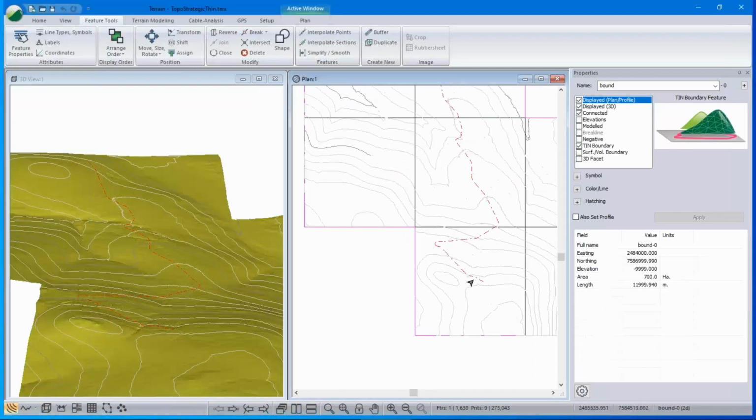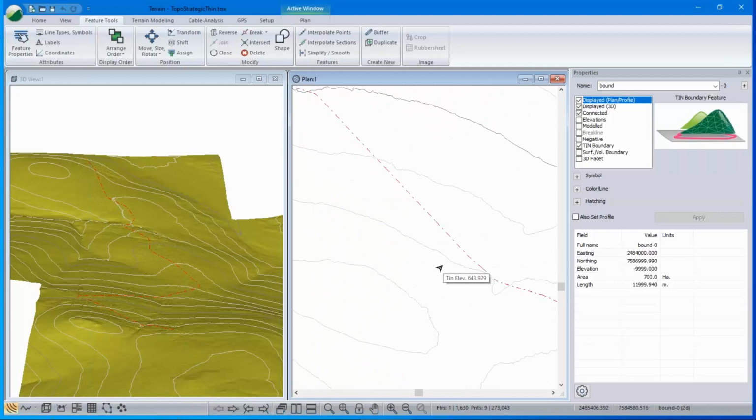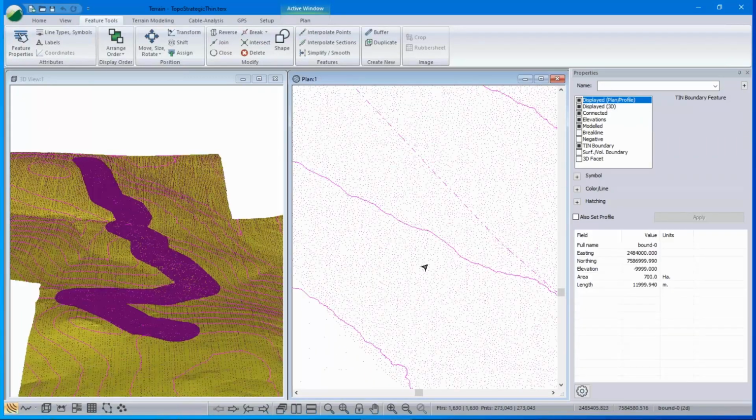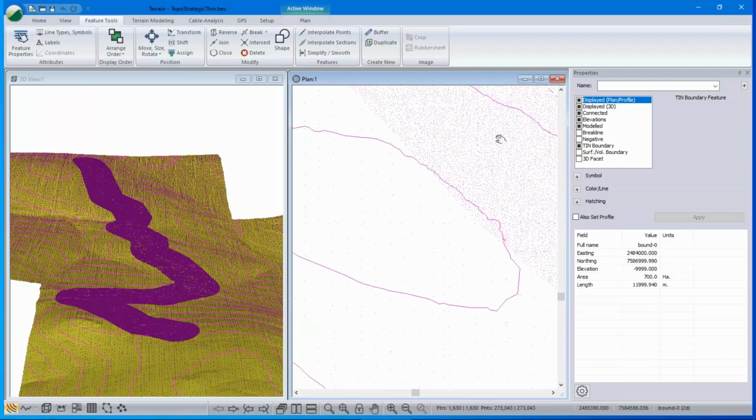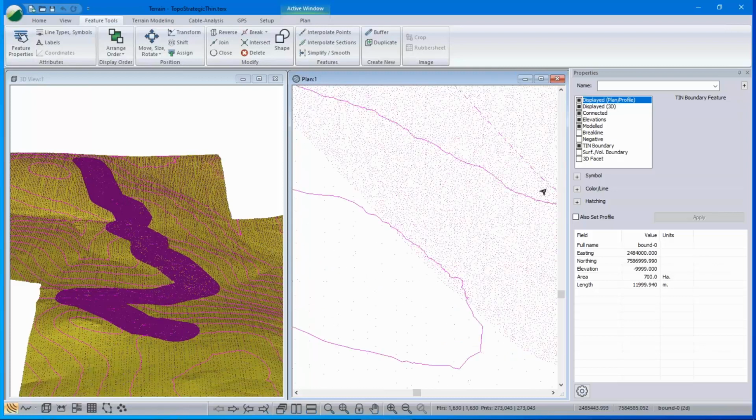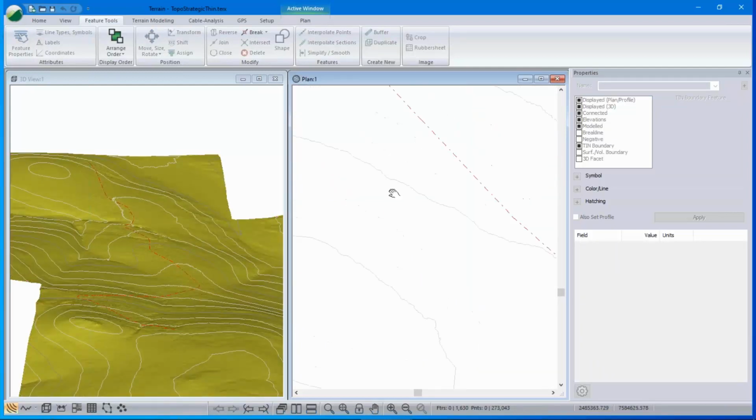If we zoom in on that, and again show all the hidden alignment points, and just type in Control A, you can see here that we've got dense points near the center line. That's 100 meters there. Here's my thinned data. So we've got strategic thinning, but this came from the LiDAR. So I'm not going to actually do the thinning operation. Again, it takes a little while when there are areas of interest involved.